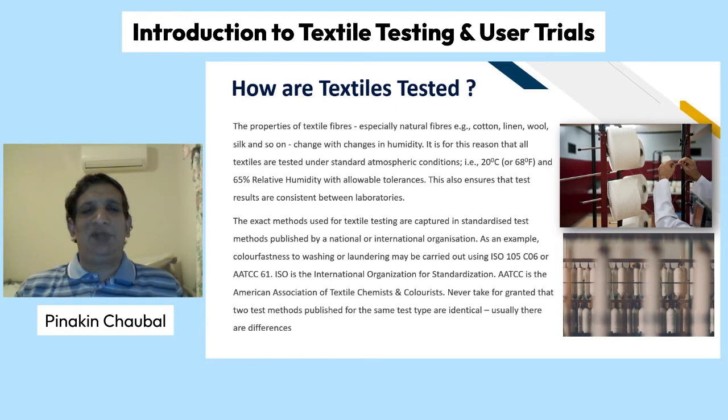The properties of textile fibers, especially natural fibers, for example cotton, linen, wool, silk and so on, change with changes in humidity. It is for this reason that all textiles are tested under standard atmospheric conditions, i.e. 20 degrees Celsius or 68 degrees Fahrenheit temperature and 65% relative humidity, with allowable tolerances. This also ensures that test results are consistent between labs.